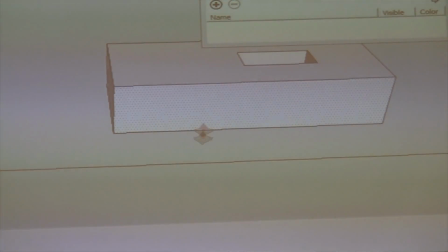So I assume there's an undo in case you make a mistake. Yes, there's always an undo. So from here I can come up 5. You'll use it now. Oh yeah, I always do. Now if I put a rectangle over here, it comes in that same direction. Most of the time that you use the double click is whenever you're on the same surface, just drawing another piece. But I wanted to show that to you because you're going to say to yourself, what just happened? It can throw you, but it has to do with the orientation of the surface.